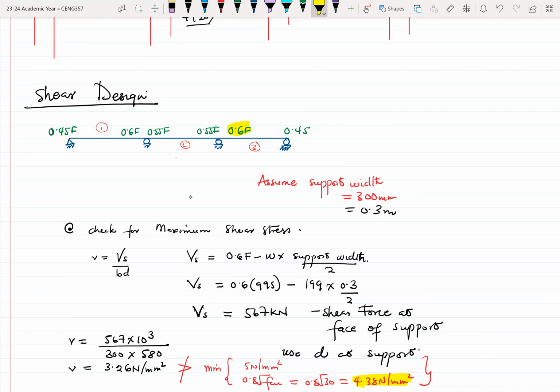What makes design interesting is that most decisions are from the point of view of the structural engineer. Before I go on and do the calculation, some structural engineer would decide, okay, instead of me finding the shear for each span, I can pick the higher value and work with that, and whatever I get, I apply to all the spans.